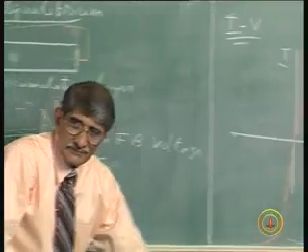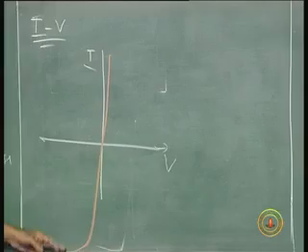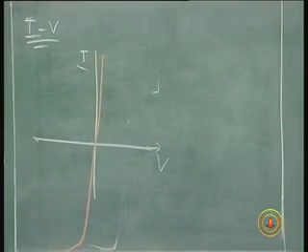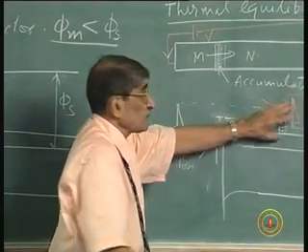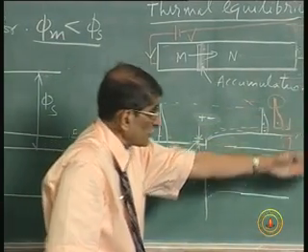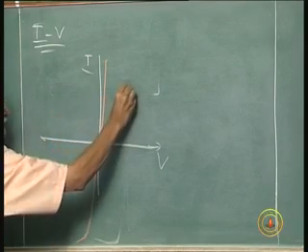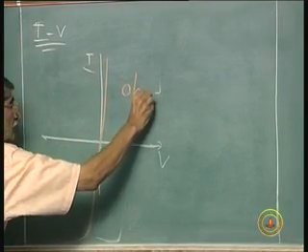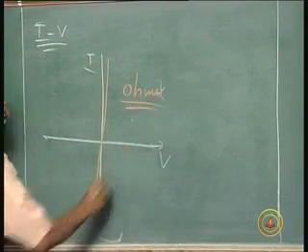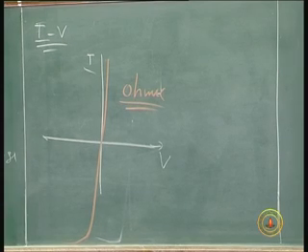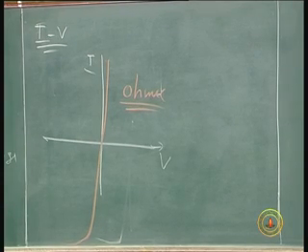You may have to go down there to get right up to that point. Very leaky diode, because almost all of them will be able to cross once you bring this down. With a very small voltage, large current will flow through. So, this is an ohmic contact. Close to ohmic contact. So, there is no trick.